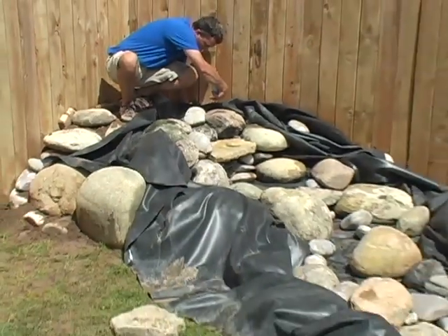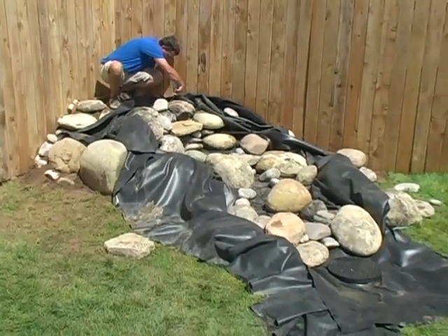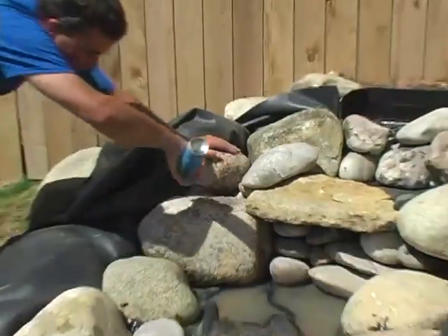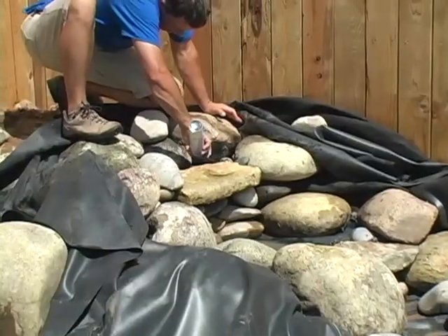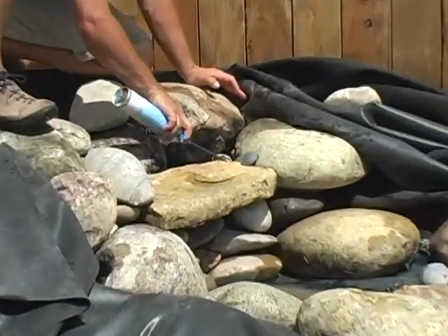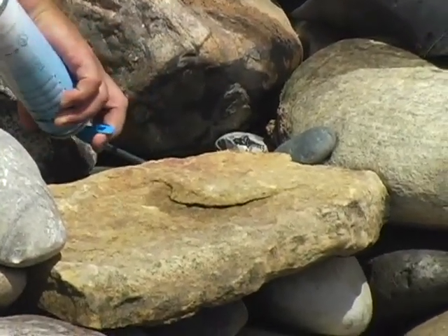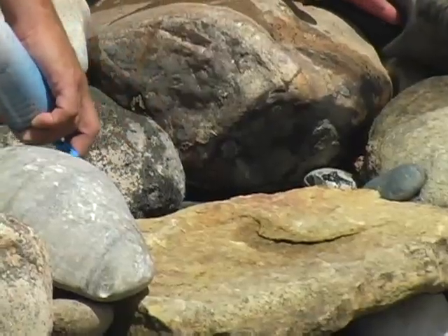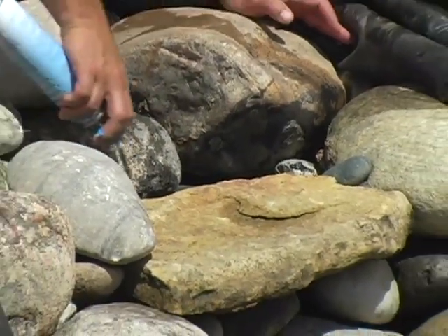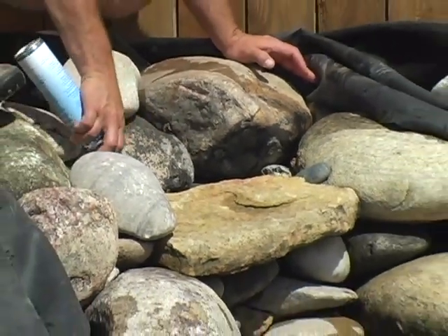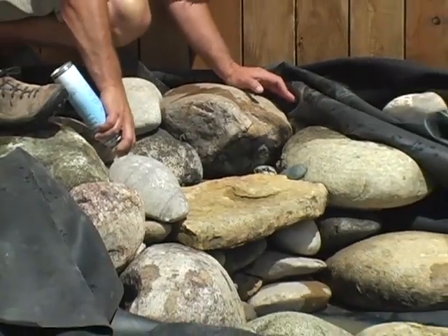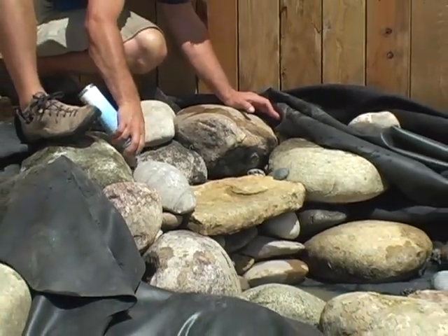Expanding black foam redirects water flow over rocks, filling in cracks and voids to create a professional-looking waterfall. It adheres best to cool and damp rockwork. Start at the top of the waterfall, working your way down in the direction of the water flow. The idea here is to seal up gaps underneath and between rockwork from the upstream side.